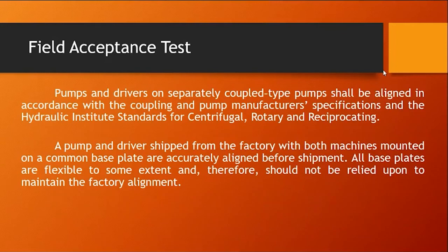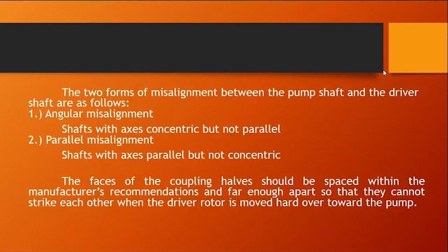Field acceptance test. Pumps and drivers on separately coupled type pumps shall be aligned in accordance with the coupling and pump manufacturer's specifications and the Hydraulic Institute standards for centrifugal, rotary, and reciprocating pumps. A pump and driver shipped from the factory with both machines mounted on a common base plate are accurately aligned before shipment. All base plates are flexible to some extent and therefore should not be relied upon to maintain the factory alignment. The two forms of misalignment between the pump shaft and the driver are as follows.